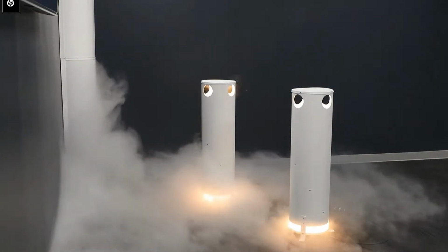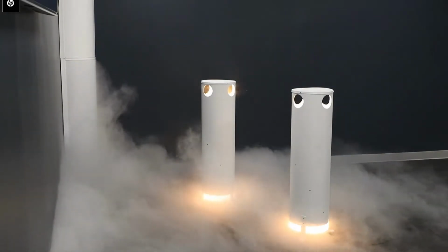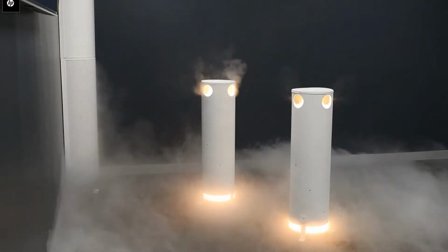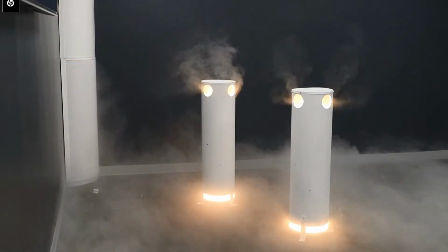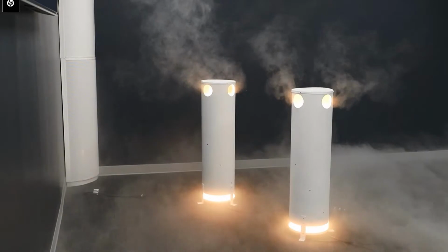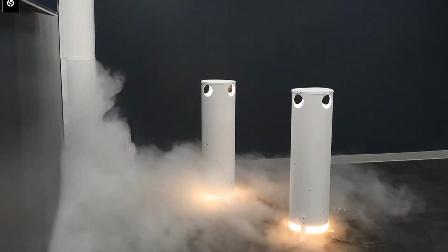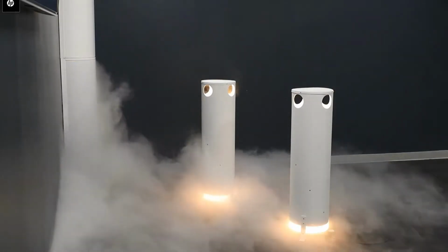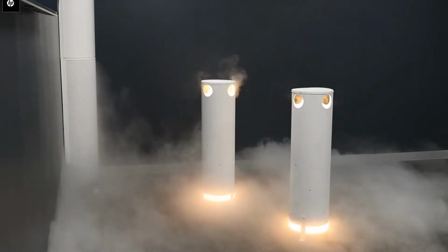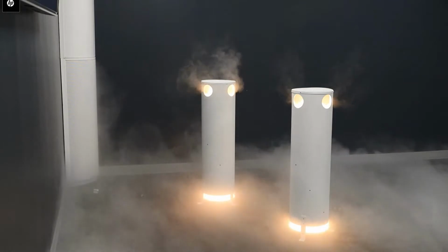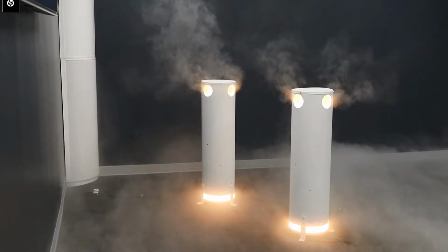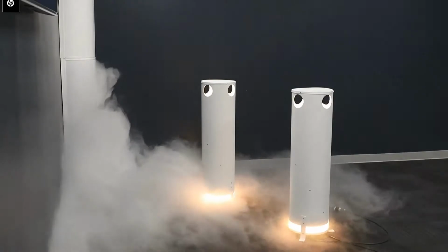Then our occupants, which are simulated by these white cylinders in this video, whether it's ourselves or electronic equipment or any other heat load within the space, are generating heat that is warming the air around us, and warmer air is more buoyant and thus must rise. So a displacement system takes advantage of that effect, causing all of our cool air to be at the floor and then all of our warmer contaminated air to rise up to the ceiling. This effectively creates a heat-seeking effect of our supply air directly to our occupants.